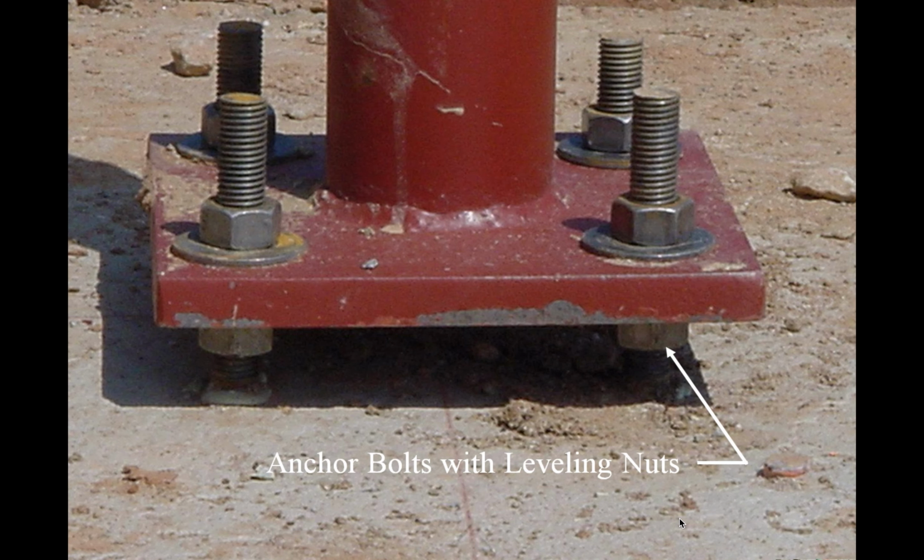Alright, so right there is an example of that. Leveling nuts can be used underneath it, and what that does is, sometimes the concrete that was poured for the foundation isn't exactly perfectly level, so you don't want to base your elevation on the mating between the steel and the concrete. So what you do is you have those nuts in place, and you verify that they're all turned up to the same location.